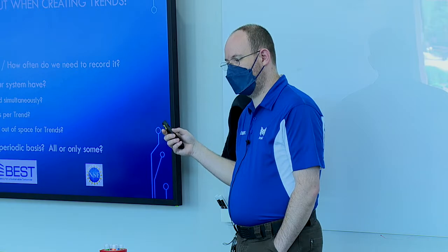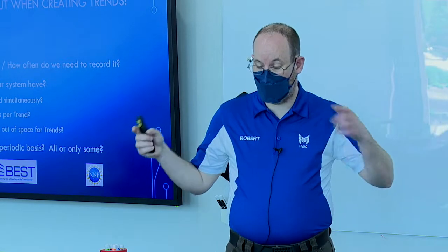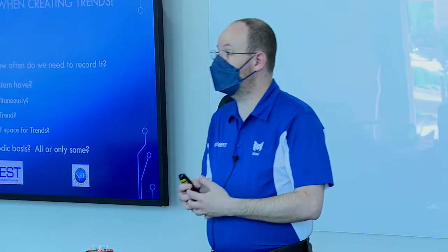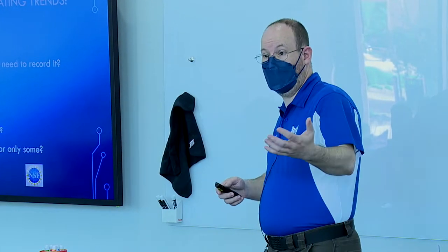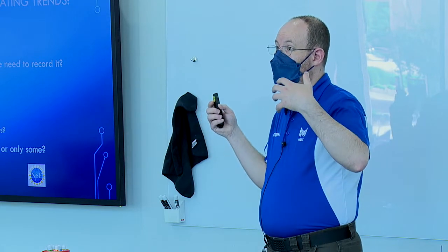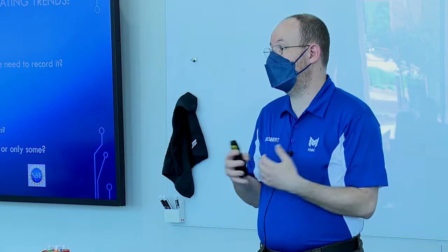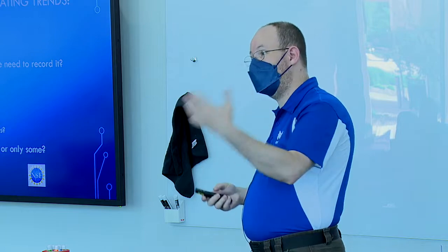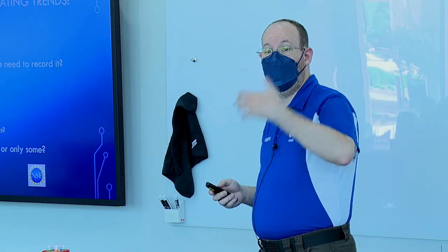So, pulling data out of systems. Because you asked specifically if we could do it with BACnet, and yes, we can. We can also generally do it very easily with LAN. Where we start running into issues is when we are dealing with proprietary communication systems. If you can't jump on the network and pull that data in the first place, it becomes very challenging. So Johnson Metasys and N2 systems are one of those classic examples.